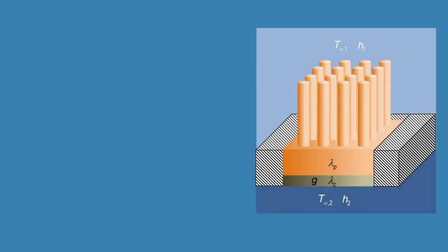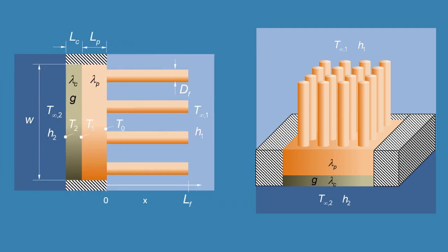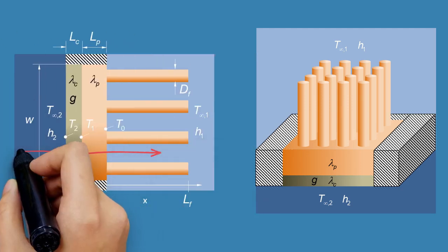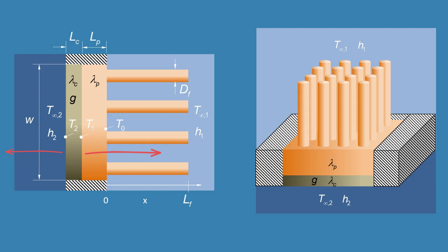The problem to be solved is the calculation of temperatures and heat transfer rates for an electronic chip with a heatsink. To keep the conduction one-dimensional, we will consider the sides of the set to be insulated. The fluid on both sides has different temperatures and convection coefficients.